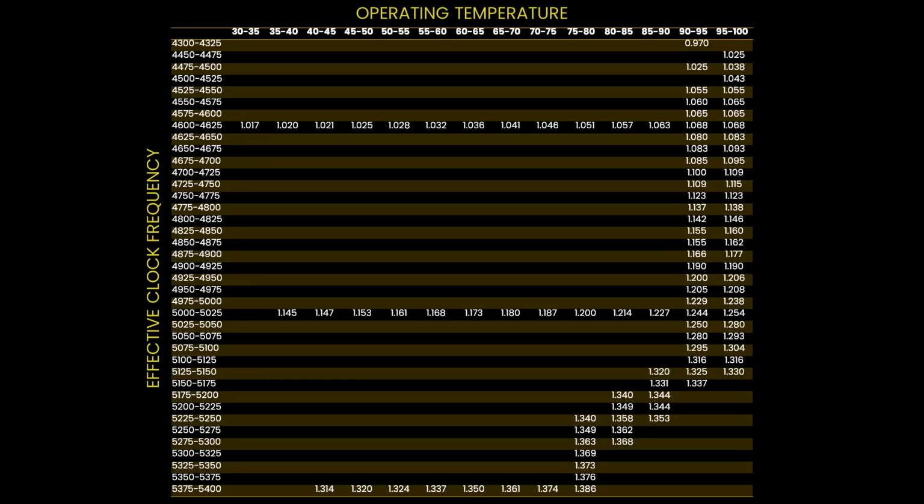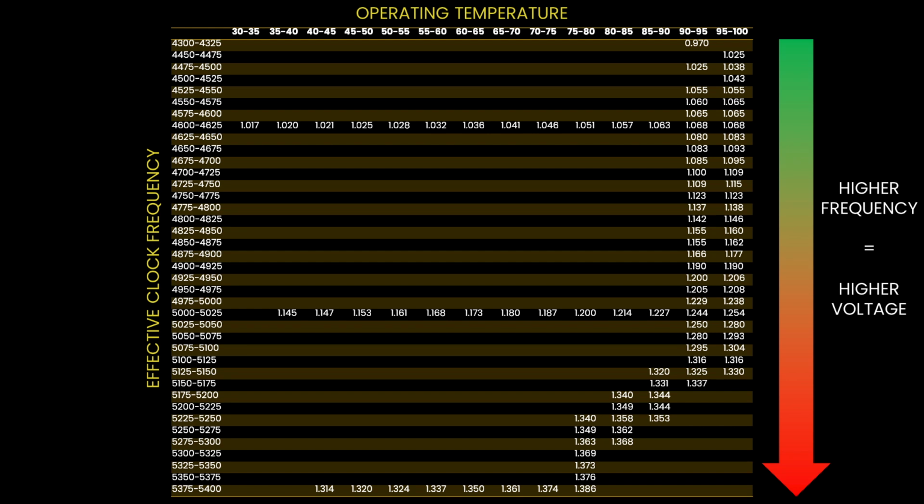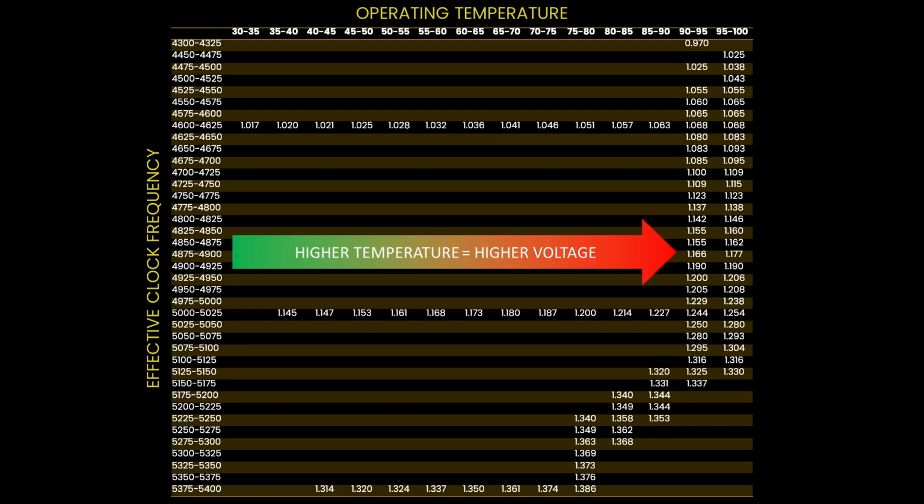While extracting this VFT table from the CPU cores is not possible, I can still somewhat illustrate how it works. In this case, I assigned a workload to a specific Zen 4 core. I tracked the VID request across the different frequencies and temperatures. We can make 3 observations from the table. First, obviously, for higher frequencies, the CPU needs higher voltages. Second, for a given frequency, the CPU requests higher voltages as the temperature increases.